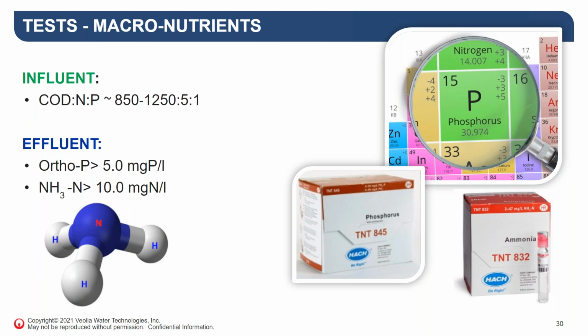So I know that it's going in there, and what I'm assuming is happening is that the nitrogen's all going to new sludge growth, which is okay, all right? And I don't care that I have less than 10 milligrams of ammonia nitrogen in the effluent, again, because in these particular cases, I have 0 VFA, I get good sludge growth and really good COD reduction. So I really don't care.